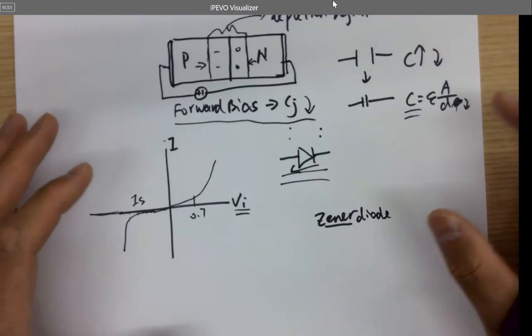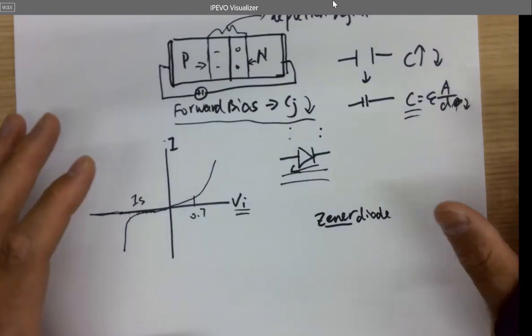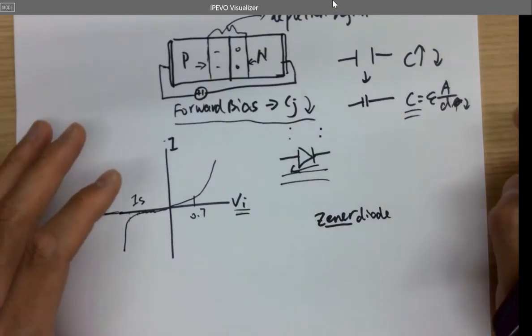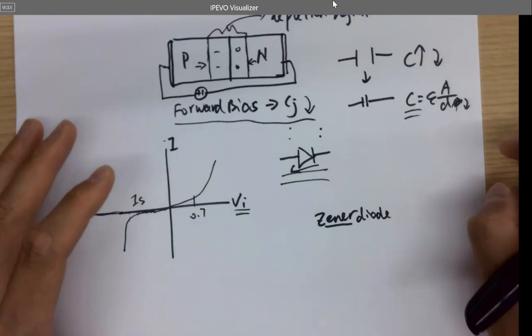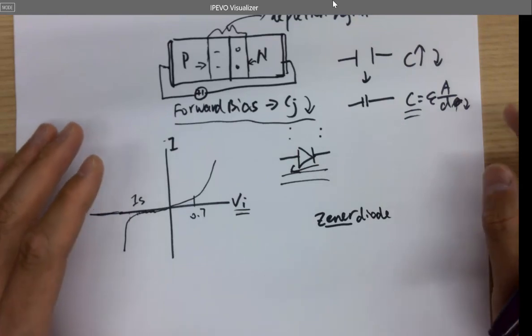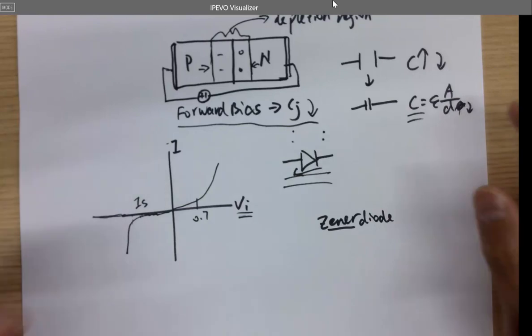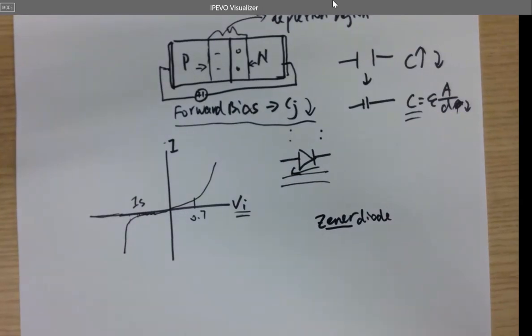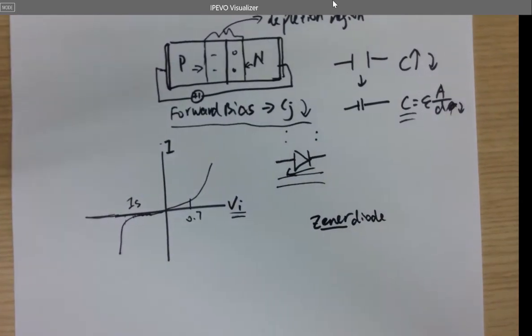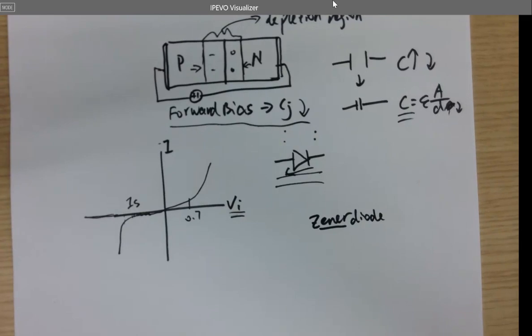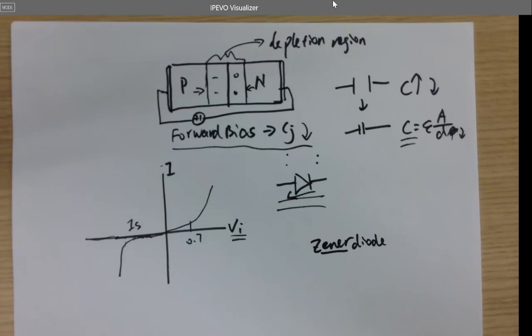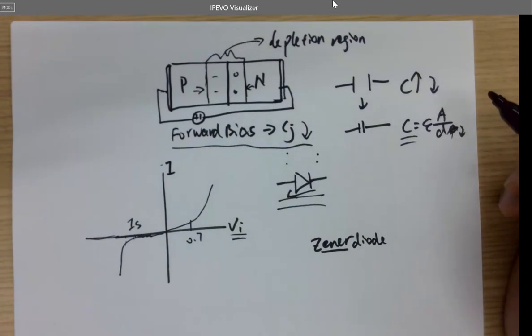But when you guys are building a power supply module in the future, never pick up the Zener diode in the lab. I have seen so many students in the past sourcing components in the lab drawer. If they couldn't find a regular diode, they just picked up a Zener diode to use as a diode in the power supply module. Really embarrassing in class.